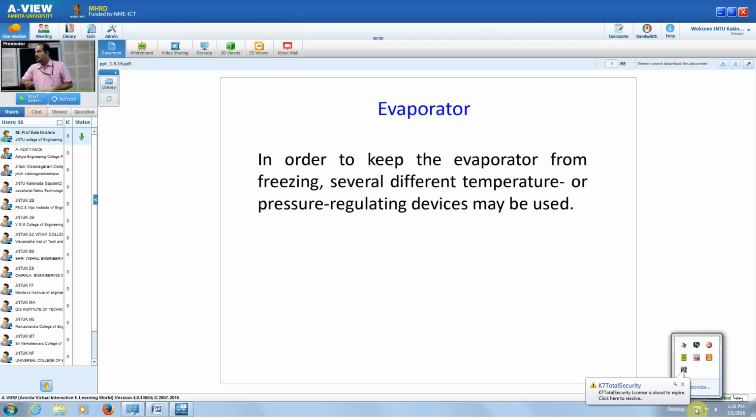That's why suddenly we will operate a manual button, maybe the thermostatic expansion valve, maybe the sensors. When you press the button, automatically the compressor will be tripped. After some time the compressor is not working, so the outside temperature being higher, the ice slowly tries to melt.